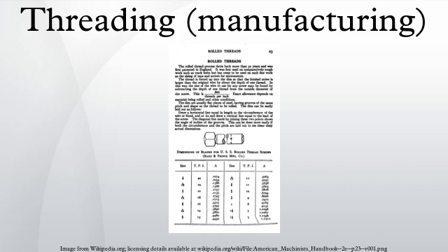Center-type end-feed thread grinding uses a grinding wheel with multiple ribs that is longer than the length of the desired thread. First, the grinding wheel is fed into the blank to the full thread depth. Then the blank is slowly rotated through approximately 1.5 turns while axially advancing through 1 pitch per revolution.